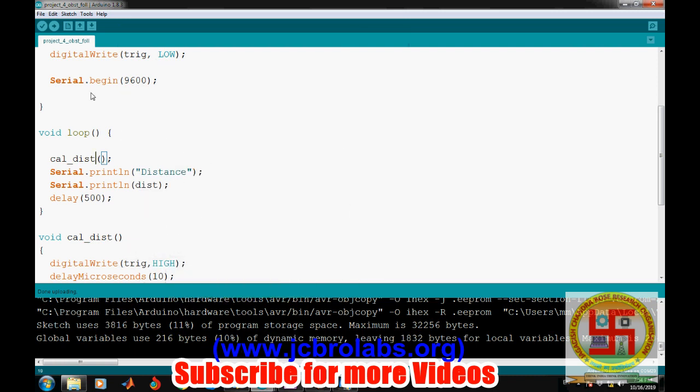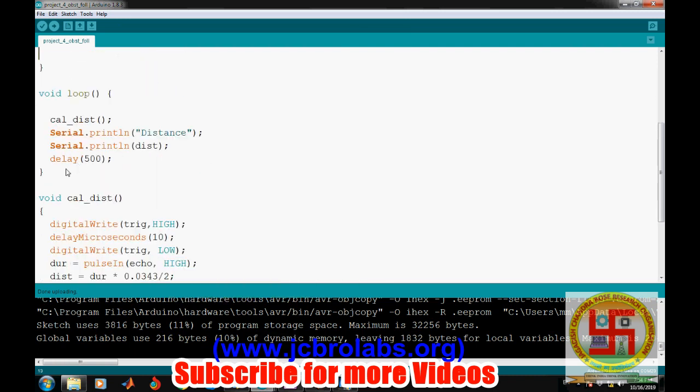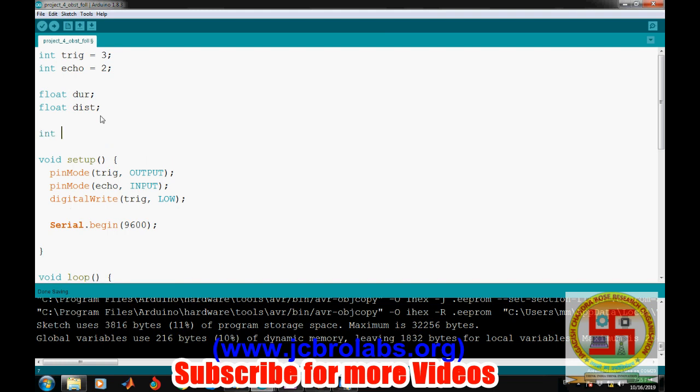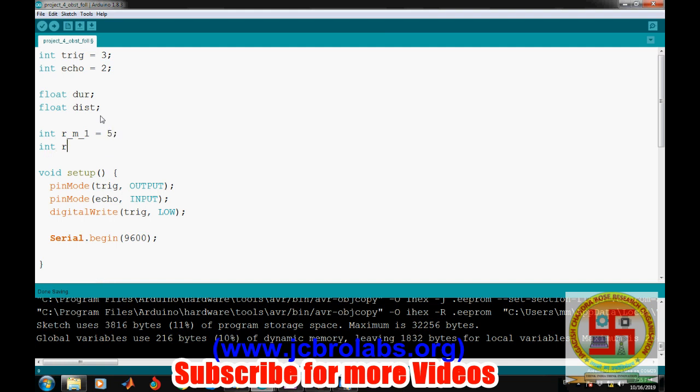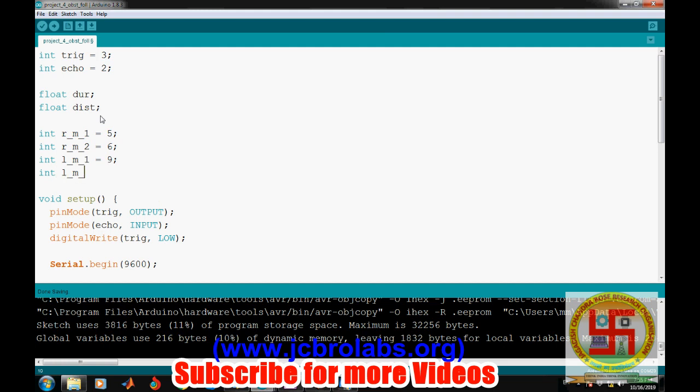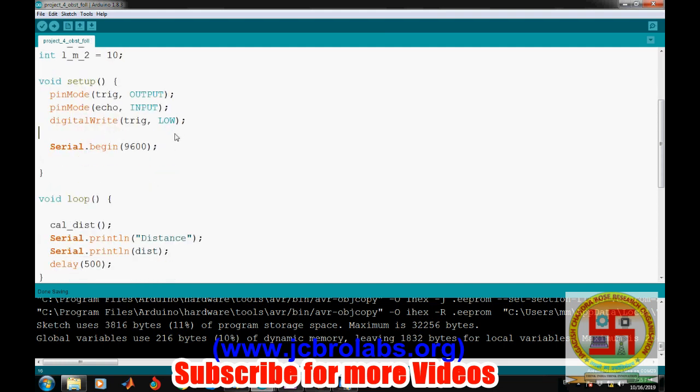Okay, so now we'll move forward. Once the distance has been calculated, now we will add a motors program into it, like when we want to turn on the motor, when we want to stop the motors. So for that let's define the motor pins, right? So int R underscore M underscore 1, its first pin, is connected to pin number 5, and then int R underscore M underscore 2 is connected to pin number 6, and then left motor L underscore M underscore 1 is connected to pin number 9, and then L underscore M underscore 2 is connected to pin number 10. Right, now we need to define the pin mode of all these pins.